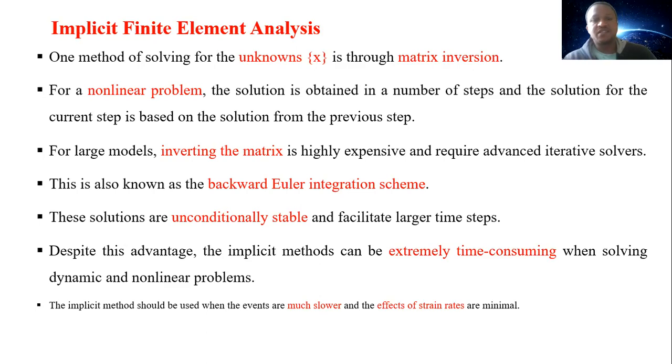This is also known as a backward Euler integration scheme. These solutions are unconditionally stable and facilitate large time steps. Despite this advantage, the implicit method can be extremely time consuming when solving dynamic and nonlinear problems.